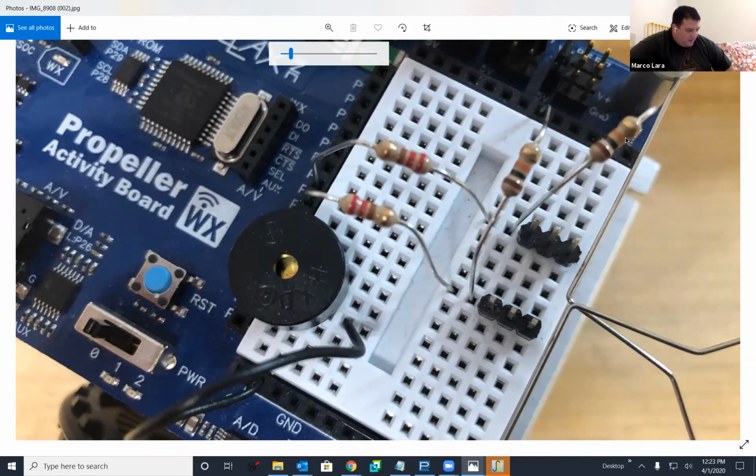That was more to make sure your motors are working okay. But I also made sure the resistors weren't touching each other anymore. Yep, that's the most likely culprit right there, that 2 resistor leads were touching each other. Yep, that's probably it.